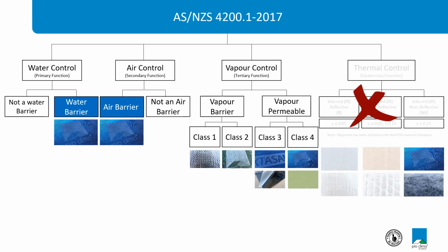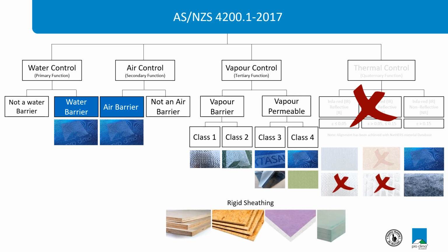So what we end up with is selecting your water barrier and air barrier such that it can be installed using proper seals and junctions to create a proper weather resistant barrier, but then selecting the right vapor diffusion properties on the external rigid boards and the external weather resistant barrier membranes to make sure that you don't trap moisture behind them.